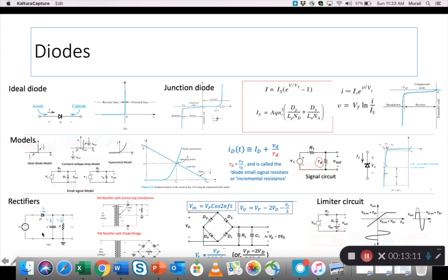So I show here a half wave rectifier to the left, where we only have one diode and a capacitor and a load resistor, right? Now you can have a rectifier without a capacitor, in which case the ripple will be very high. So to reduce the ripple and to introduce a simple filter, I mean, you can have very complicated filters, RLC circuits and all that, but we only studied the simplest possible filters. And so the capacitor is a filter, and we derived some expressions for the output voltage, the ripple and all that for this filter.